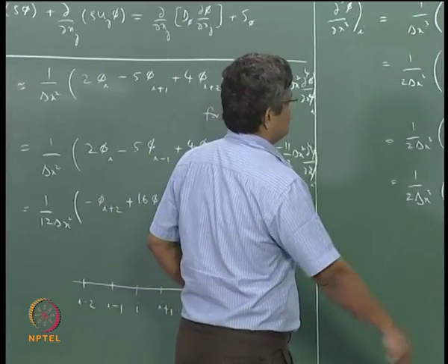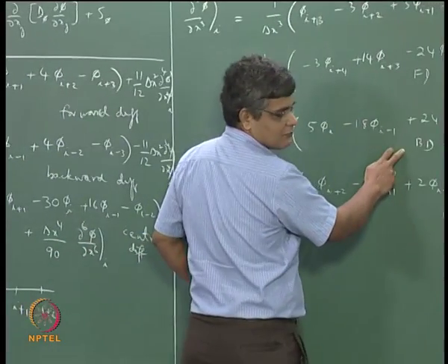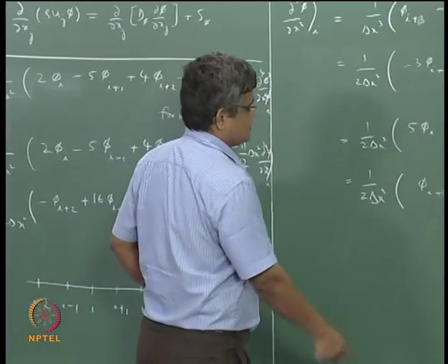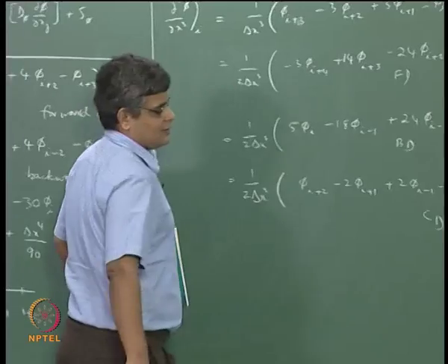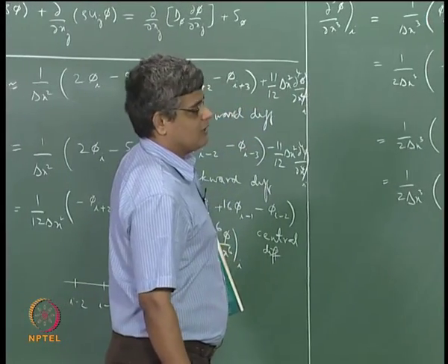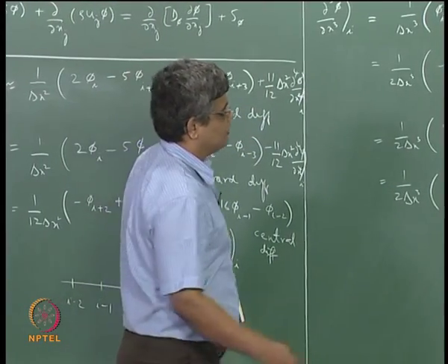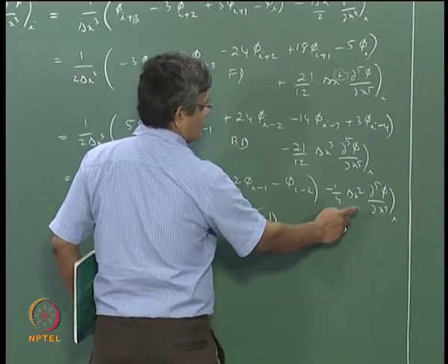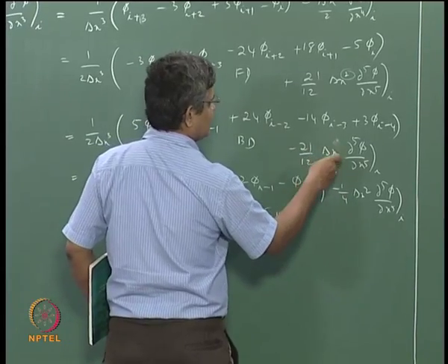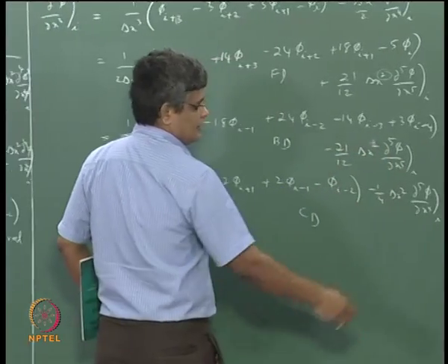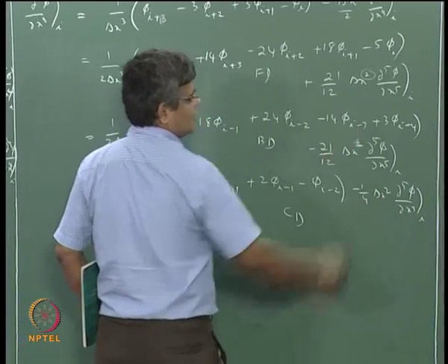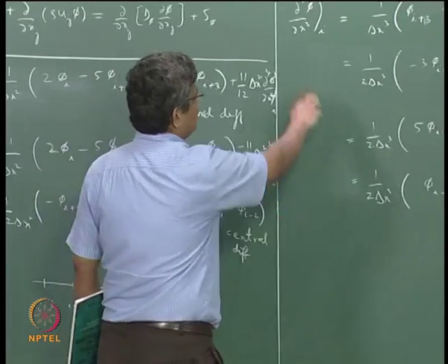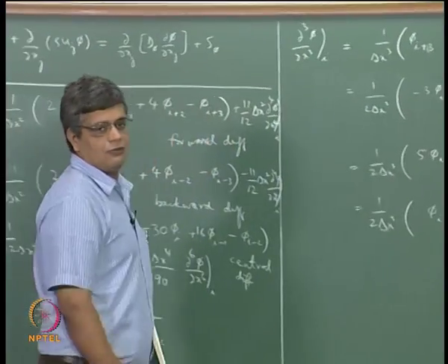And using forward differencing and backward differencing we can take account of the boundary points, and using central differencing we can approximate for all the interior points, so that we can maintain, using these kind of formulas, uniform order. This must be delta x square here, uniform order of discretization or finite difference approximation for a particular derivative throughout the fluid domain.